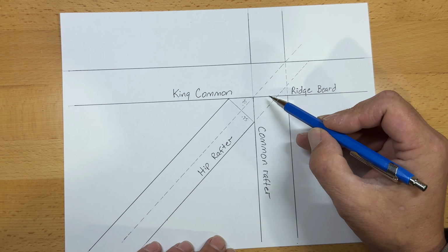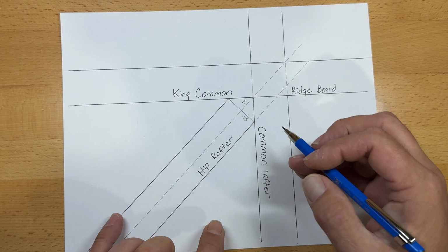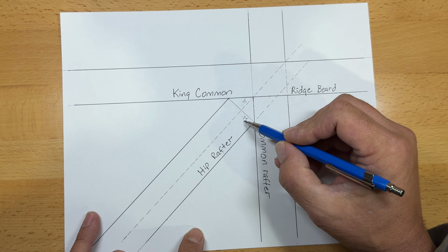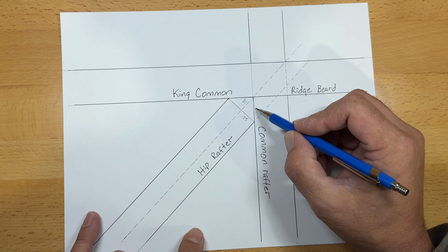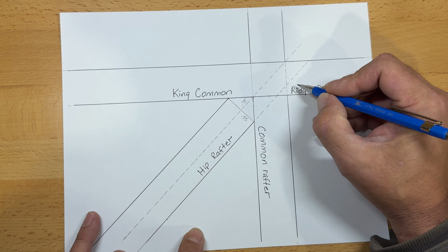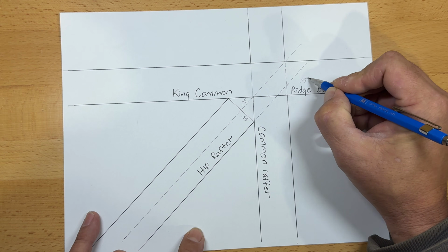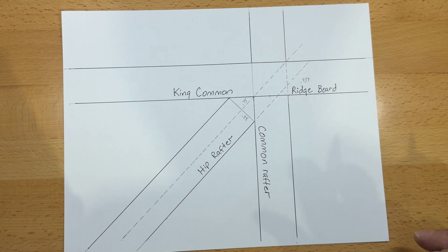It actually doesn't calculate to the theoretical center either. And because we're using dimensional lumber, this is fairly easy to prove. So building on the last video that I showed, using the Pythagorean theorem, we can very easily calculate all of these different lengths. And I can tell you that this distance here is going to be equivalent to 0.439 when using dimensional lumber. So the way we do this is like this.